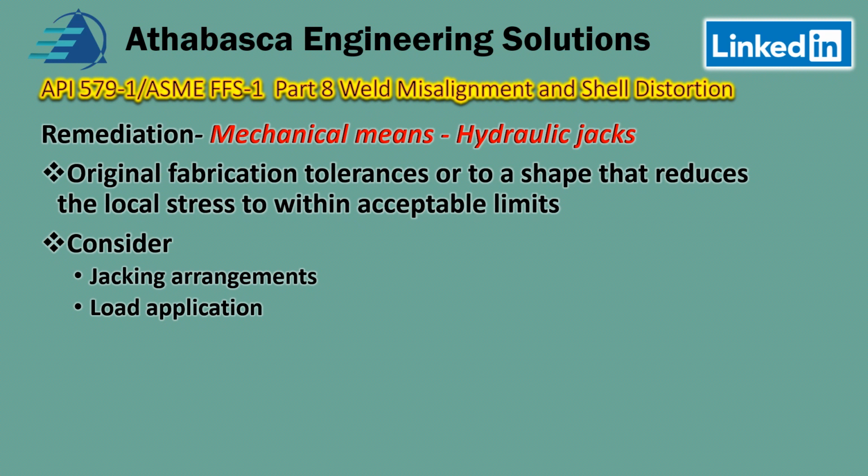Is it gradual, or is it just a quick type of load? Those things have to be considered, because the rate at which a load is applied or let go can add additional stress to a part. The next one is what kind of monitoring would be done to ensure that the loads are being applied properly, and also to ensure that there's no cracking development and so on.